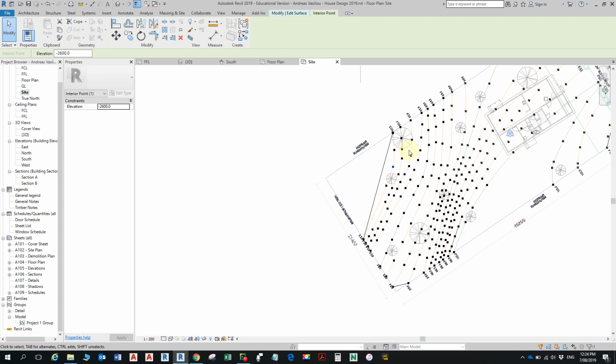All right. So if we do a minus 5,000, this is making sure I'm seeing everything, and probably most people will see everything. It wouldn't be 5 meters below. It'd be pretty close to where the house level is. So good. So mine is minus 2600. Whatever the number is, if it's an odd number, like 10.5, whatever, and you're not going to remember it, write it down or click here, Control C, copy it, and then you can just paste it in the new point later, exactly the same.